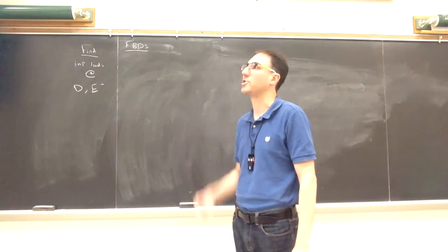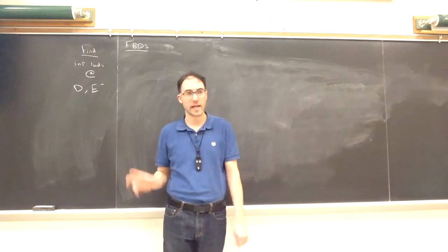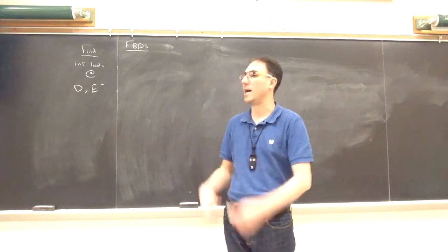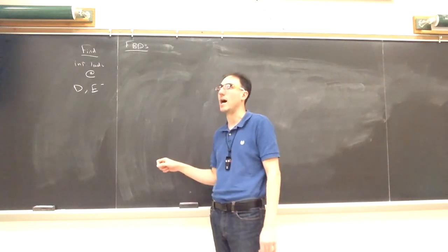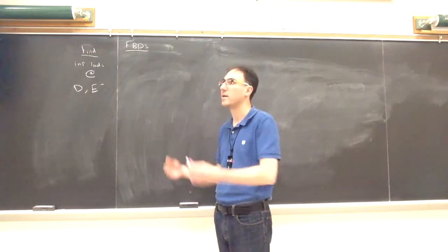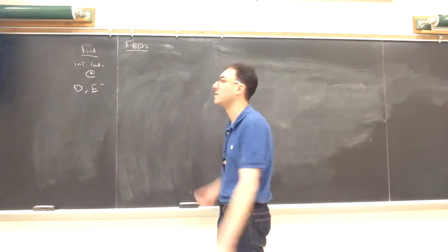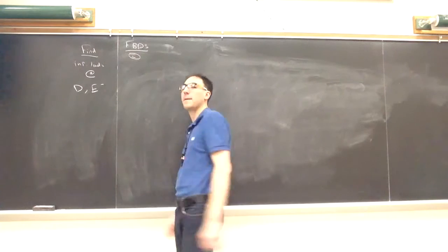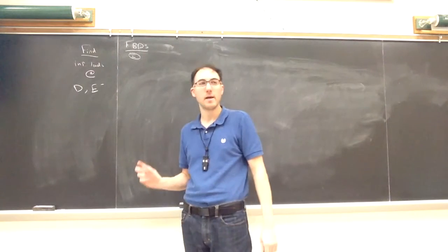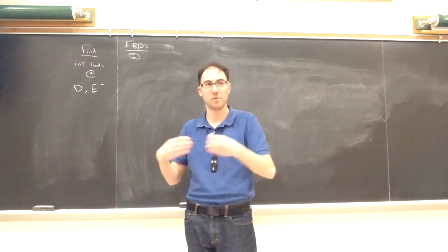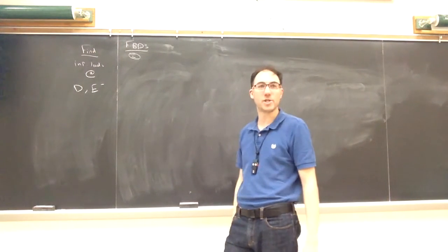However, we do have a pin connection at B, where we can treat this like a frames and machines problem. So this is actually an internal forces problem inside a frames and machines problem. And the frames and machines problem we have to resolve first. Then we can go inside and start the new topic, or the new material, on the internal forces. So for my free body diagram step, I want to split this up. I'm not making an internal cut, which is to say I'm not finding internal forces, but I am making individual free body diagrams of the members that I'm separating. Because in this case, I can separate it at B, which we're going to treat as a pin connection.